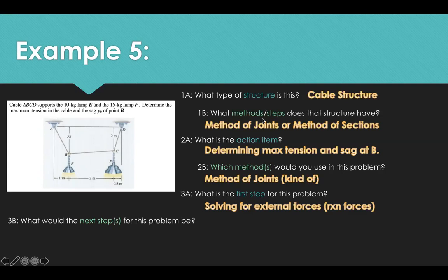Exactly. Because all free body diagrams are a description of all the forces acting on your body, you can't put a mass on a free body diagram, because a mass is not a force. So you would convert this mass to a weight by multiplying it by gravity. That's the big thing you have to do here. Because it's kilograms and not newtons, you would have to multiply by 9.81.